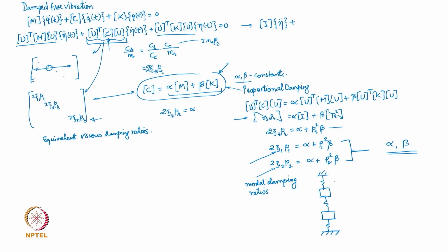So then what you do is excite it the way we do the RAP test, and you will obviously get many modes excited, and the time domain data will have contribution from several modes. We have seen that general excitation is not going to excite only one mode. It may excite at least the first few modes quite strongly, and then you can filter this out and get each frequency response, and from that time domain data you can find out the damping ratio. You know how to find that using logarithmic decrement.